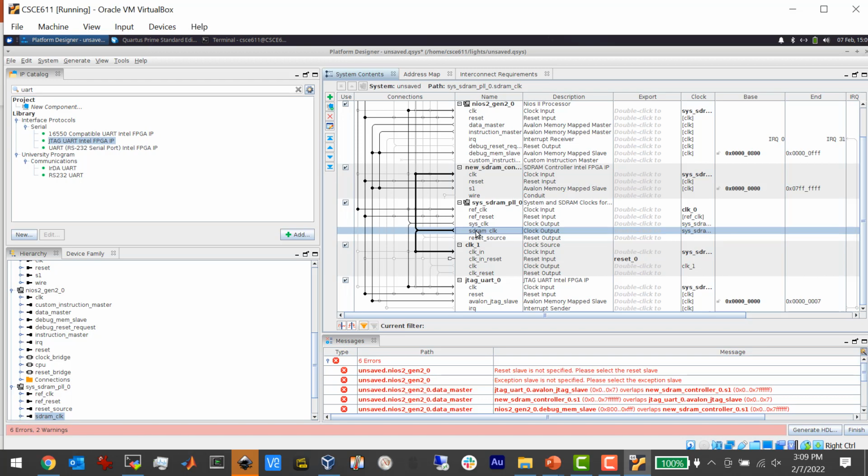I told you it was going to be a little confusing, but like I said, this is the kind of process they use when Apple creates a new chip for the iPhone. They pick components from a repertoire of IP blocks, and then they connect them on a common on-chip bus, basically doing this. Not all components connect to all the other components, so you have to be careful how the connections are made. All right, and then I think that's about it.